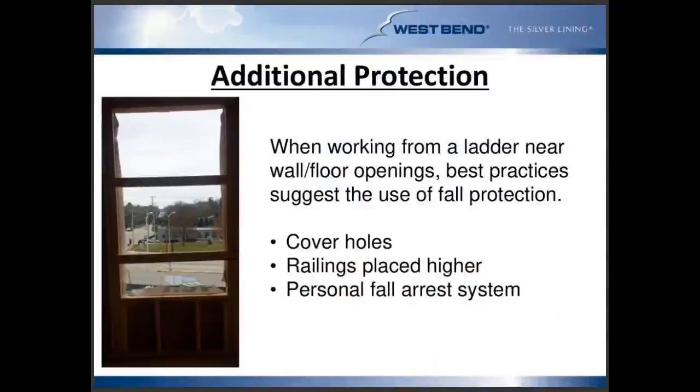Some additional protection in the event that you do need to use a step ladder close to a wall that might have an opening, or like the picture I showed you before where there was a floor opening that we were working near. The installation of maybe some taller guard railings could be an option. Again, fall protection or fall arrest might be the safest option, but if all else fails, if we are exposed to maybe a 30-foot fall out a window, like was the case in this picture that was taken, you can also install higher guard railings to prevent that from being an even worse fall than it would be if you just were to fall from the ladder.